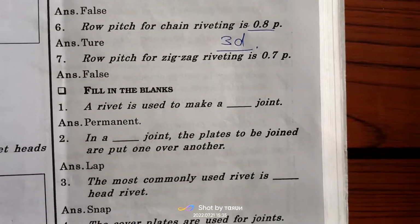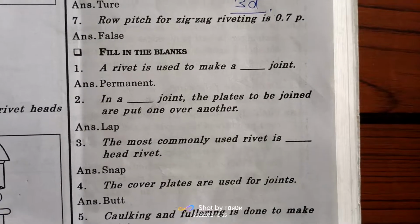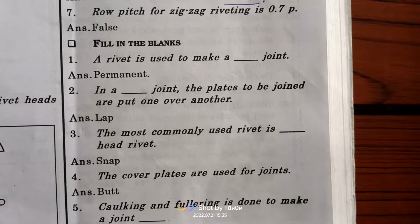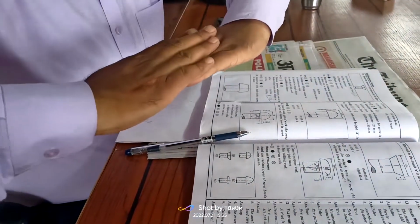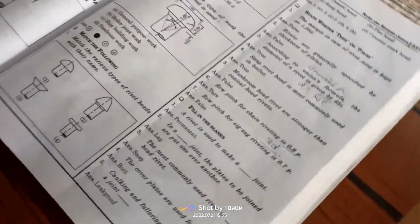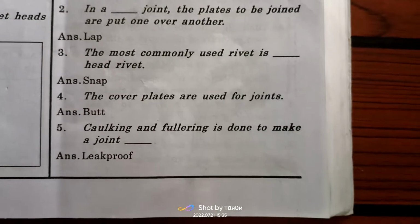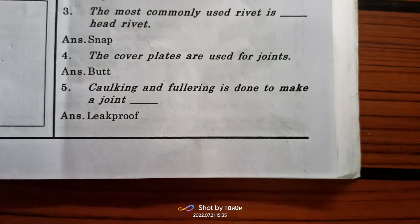Next, fill in the blanks. A rivet is used to make dash joint. Rivet is a permanent joint. In a lap joint, the plates to be joined are put one over another. One over another is lap joint. This is butt, end to end, and one over the other is lap. So it is lap joint. The most commonly used rivet is snap head rivet. The cover plate is used in butt joints. Caulking and folding is done to make a joint leak proof.